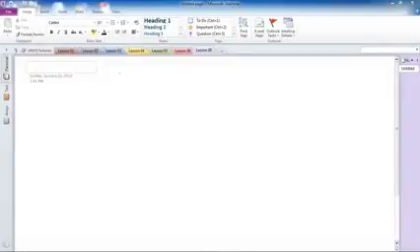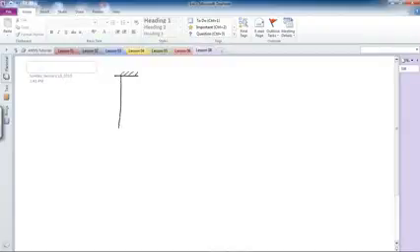So basically, if you have a beam like this hanging downwards from the ceiling, it should go straight, and the only load which is applied to this beam is its own weight from the center of mass, let's say W. We want to see how this beam deforms by its own weight applied to the beam in ANSYS. So this is the first case we're going to examine in this lesson.